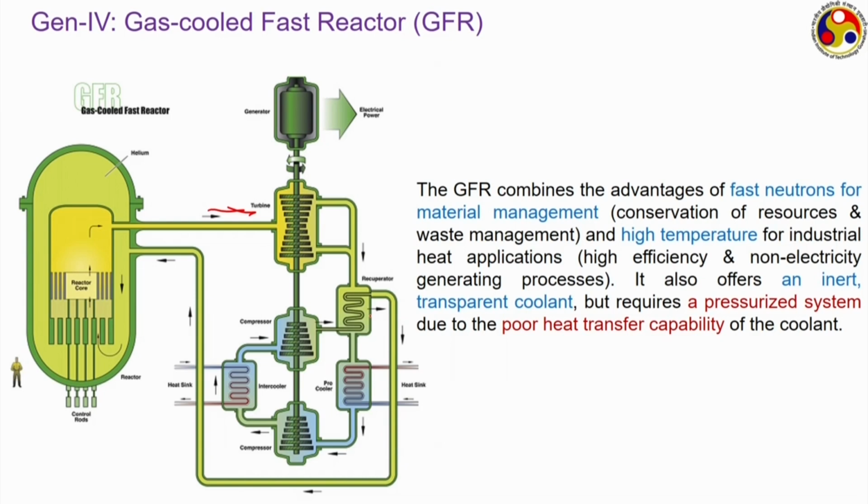And also another advantage with helium as the fluid is we are having an inert and transparent coolant. So in-site inspection or any kind of maintenance is very easy. It is an inert environment, so no problem with any kind of corrosion or any kind of chemical reaction when it comes in contact with water or air. But the heat transfer performance of course will be poor, because the thermal conductivity is significantly lower, almost negligible compared to that of sodium or lead.